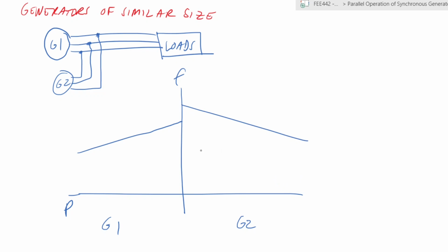Now, in this case, the two generators themselves have certain characteristics when they are supplying loads. The first of these is that the power supplied by generator 1 plus the power supplied by generator 2 must be equal to the total. That is a condition that must be achieved regardless, right? As long as the loads have a certain value, the sum total of the power being supplied by the two generators must be equal to those loads. In terms of electricity, whatever is generated must be consumed.